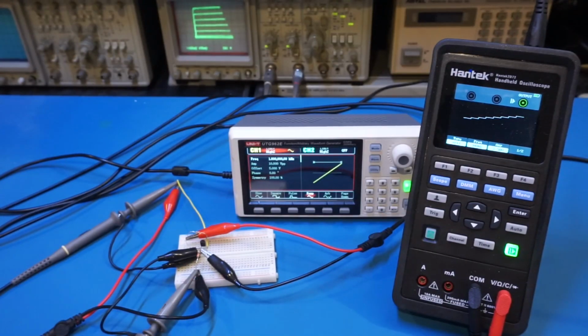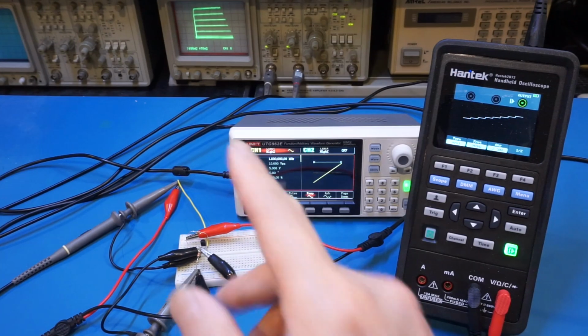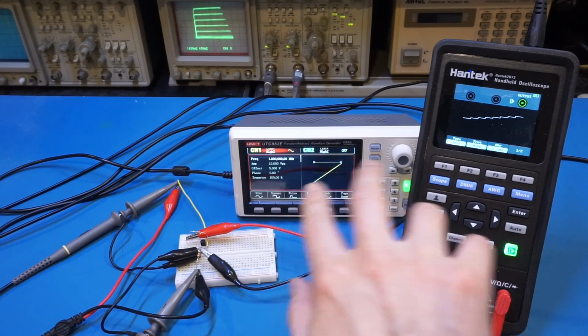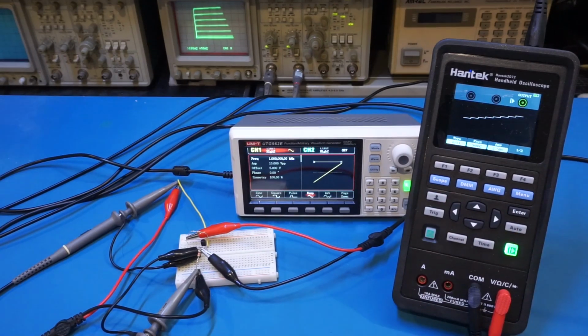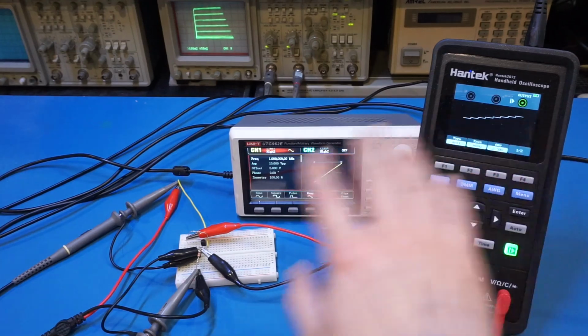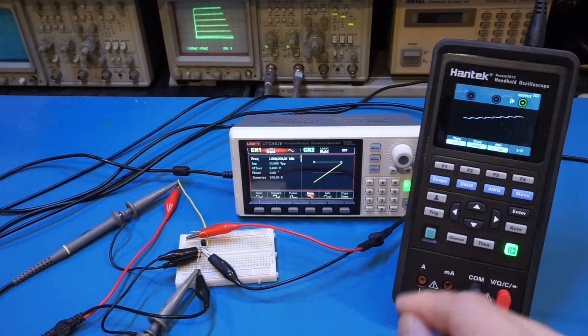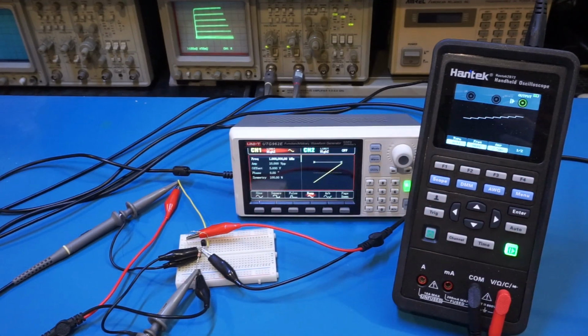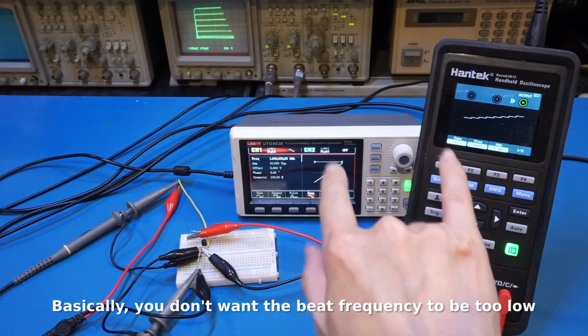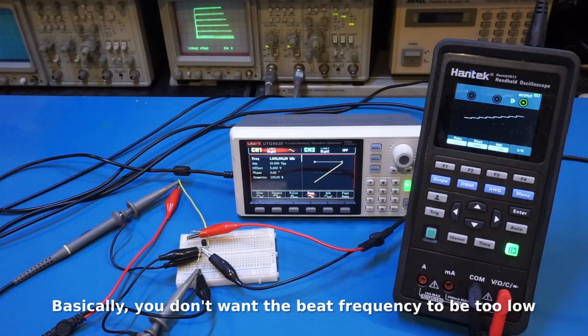One thing I wanted to point out, which is important in generating a stable image, is the choice of the frequencies of these two waveforms. Because we're using two independent signal generators, the clocks of each one are essentially running independent of each other. So in order for the display to be stable, you really don't want the frequencies of these two generators to be multiples of each other.